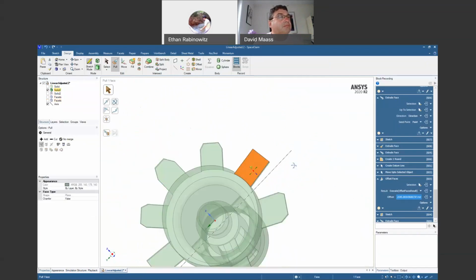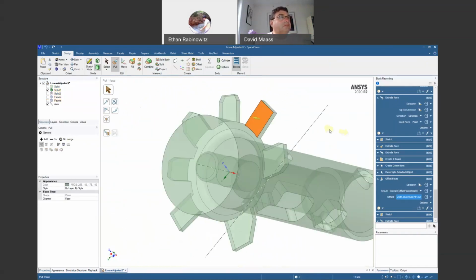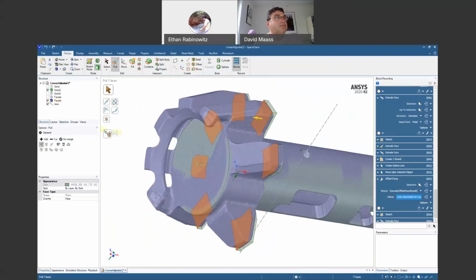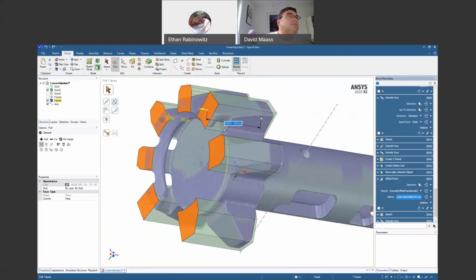There's now a few faces, but there is a trick to grabbing these. All of these are in the same plane. So there's the selection tab on the left. The first option up when I have this face selected is all coincident faces. So now they're all selected. And then if I show the facets here, I could do a pull up to and pick a point.